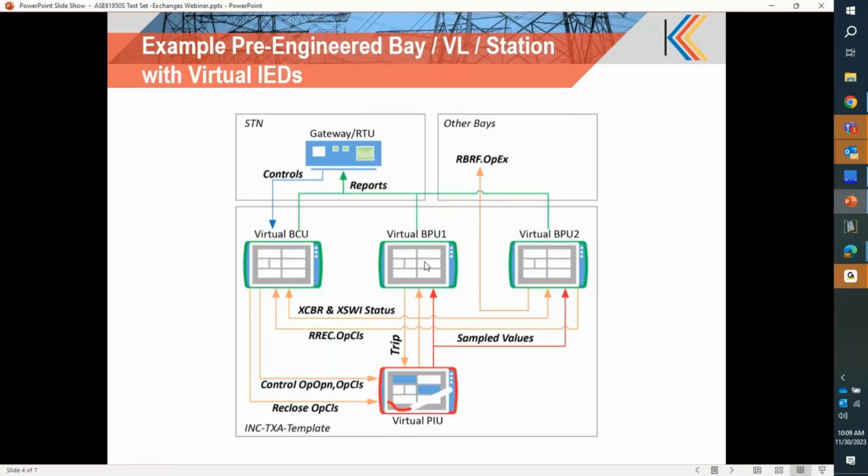This is our demo architecture slide. I'm using a pre-engineered SEL file. It's modeled after a feeder bay, and we've used this in demonstrations with other customers and often use it for explanation and providing an overview of our capabilities. Here we have a protection design that involves a couple of protection relays, a backup and a main. We're using a PIU device, or process interface unit, which acts as a combiner for the switchgear control, as well as provides a merging unit function.